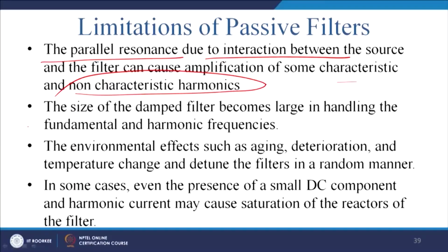Another big challenge is the size of the damped filter, which becomes large in handling the fundamental and the harmonic frequencies. This is quite a big issue, because once you have a damped filter, you want to have LC fine, and thereafter you want it to be damped. That takes a lot of space, because the current rating has to be matched; it is not that simple a ceramic resistance. For this reason, it also requires a bigger size for damping.